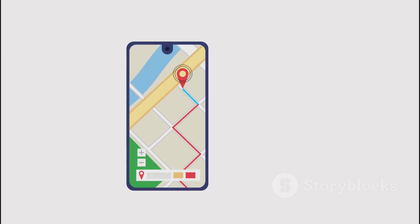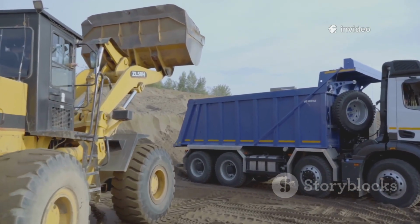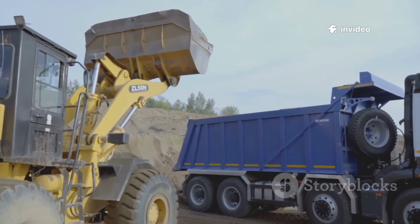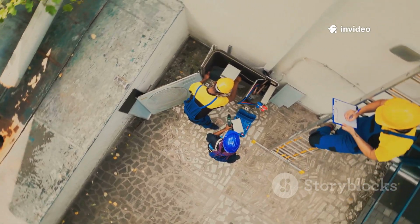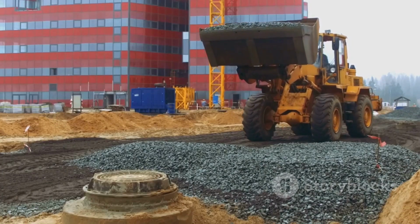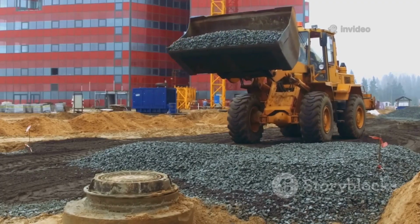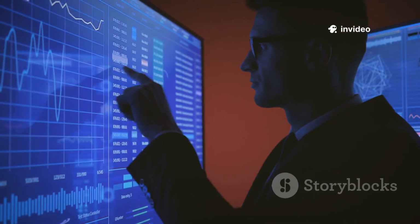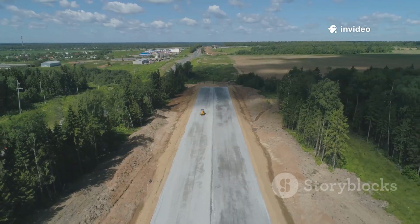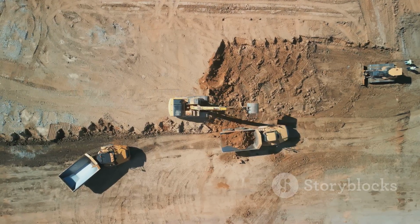Think of it like paying extra for pizza delivery outside the free zone. The farther the dirt travels, the more it costs: fuel, time, and wear on equipment. The diagram helps engineers minimize overhaul by planning smarter routes. Sometimes it's cheaper to waste dirt or borrow new dirt nearby than to pay for a long overhaul. The diagram provides the data to make those decisions. Every overhaul mile avoided is money saved. That's why the mass haul diagram is essential for controlling costs.